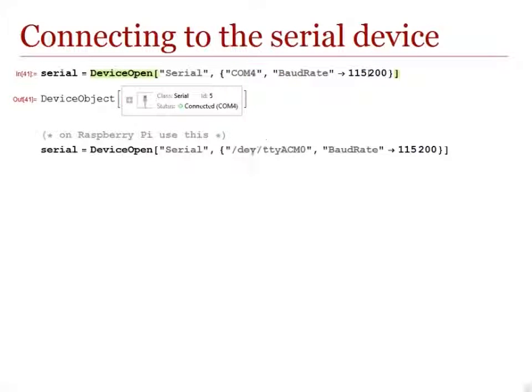For Raspberry Pi users, it's the same command. The only difference is that you need to give a different device, in this case /dev/ttyACM0, if your Arduino is connected to a USB port on your Raspberry Pi.